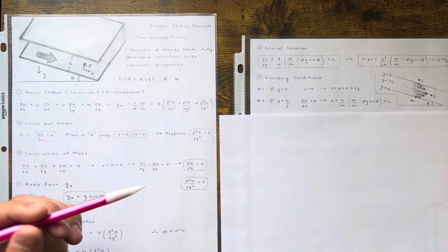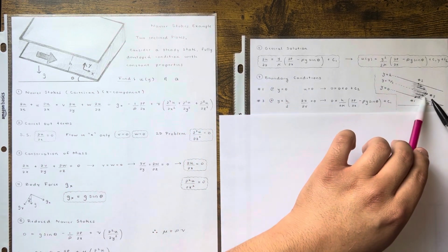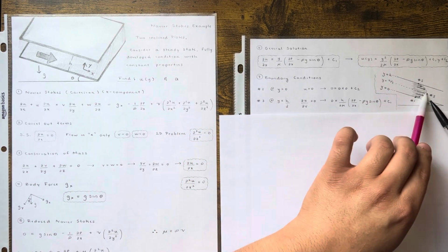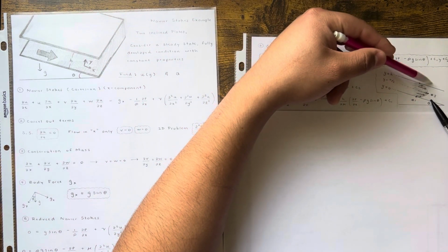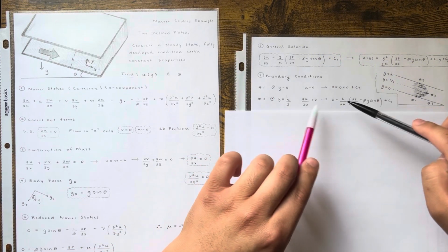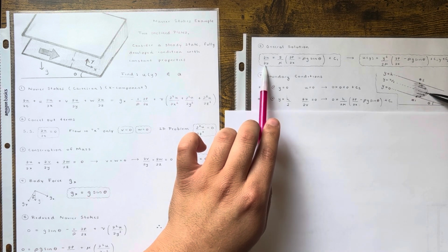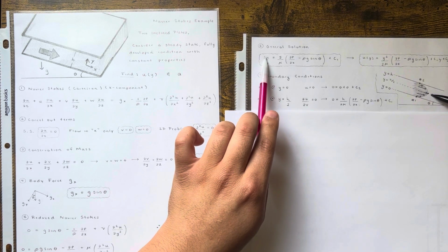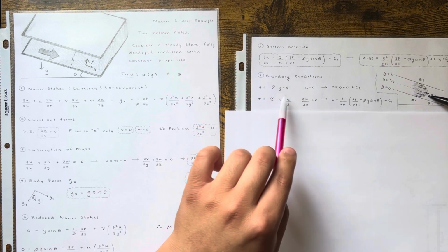And boom, you're good. What I did was I got this term, and I knew that the change in velocity with respect to y was 0 at the very center, right? Because look, take the derivative, that's just a straight line, and that's a 0 slope. So what that means is I'll get this equation. I know this, like I just told you guys, right? At the very center, the change in velocity is 0. So this is 0. And then for every y that I see, I'm going to put in an h over 2.